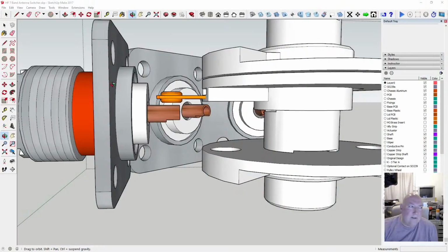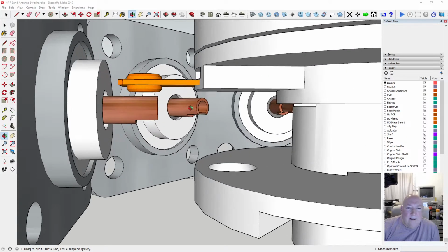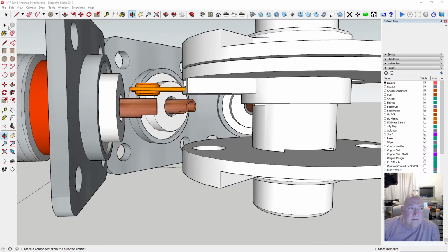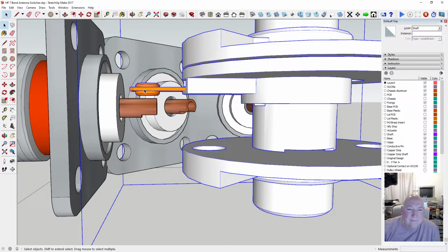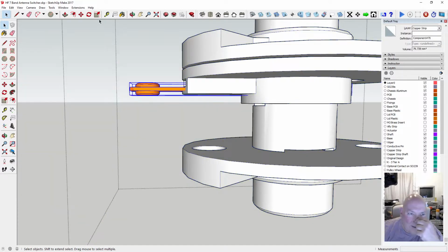Yeah, there's some play there, and it's not affecting the shaft, so probably that gap is very close to what we've got on the model. So I'll take that as gospel, and we'll purposely drop this down. I'll try 0.25 mil at a time.